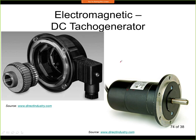I will start with the picture on the right. Here we can see that it's a relatively large sensor. In this case it has a flange to mount it to your application, so you use the holes on the flange to mount it somewhere. Here we will attach the coupling, and here we will attach it directly to our machine. It could be a speed sensor for an electric motor, for an elevator, for a conveyor belt, for an axis of some machine. This requires a coupling to connect it.